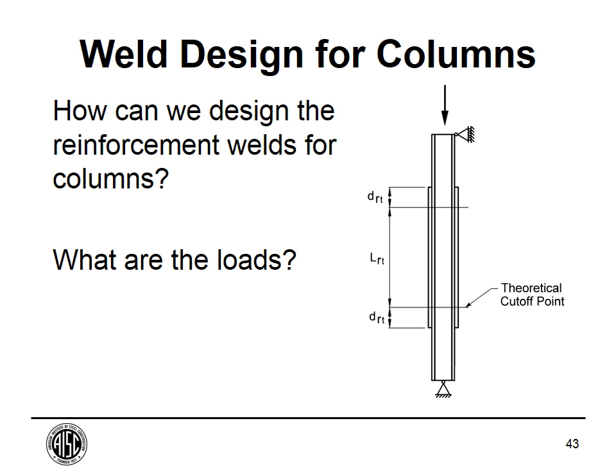So we're going to talk about how you calculate the weld strength for a built-up cross-section. We talked just a little bit about this for beams in part 1, where we had the VQ over I for the shear flow and then the MQ over I for the anchor force. But the problem is how do you calculate those loads for a built-up column?